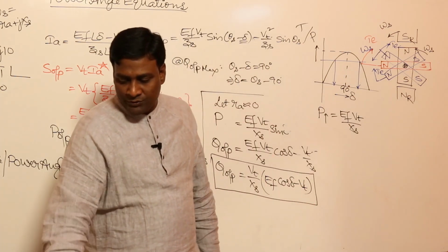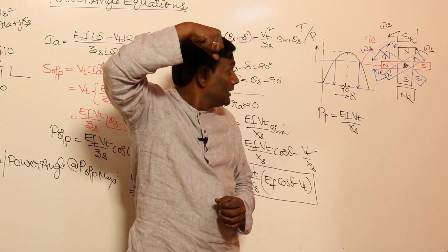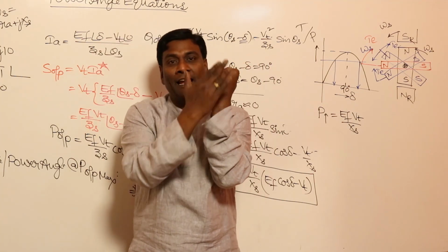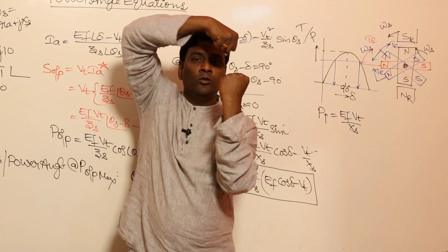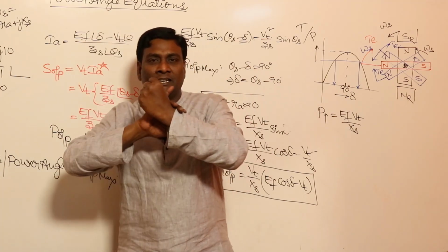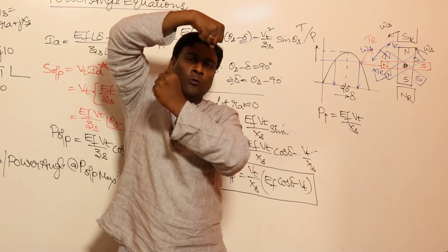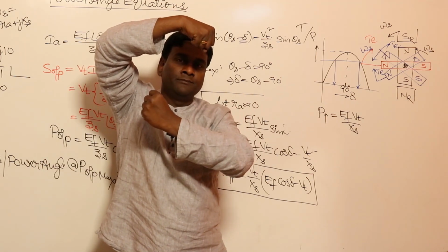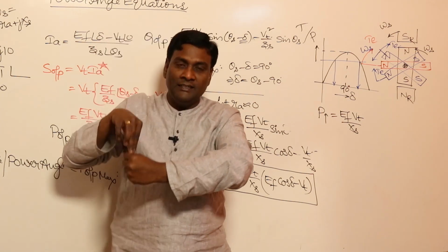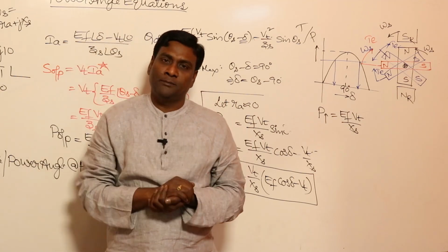Now this is the reference S pole, and this is the N pole. If both are rotating like this, torque development will be 0. If my prime mover keeps it here, both rotating in this direction, the torque will be in the opposite direction. Now if I keep it here, delta is 90 degrees, and torque is going to be maximum.